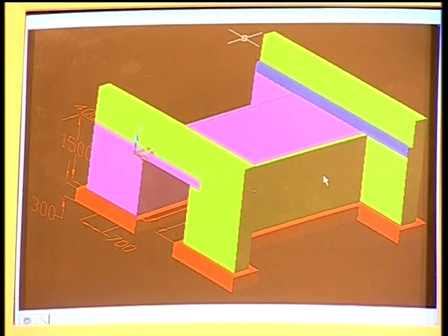This is the roadway. Now, you can see here this stream, the water in the stream will pass through this vent. This is the vent. So, here the opening is covered with the slab, so we call it a slab culvert, and in the last class you have studied about the pipe culvert. Now, in this you can see, this is the direction of roadway. So, this is the three-dimensional constructional image of RCC slab culvert.